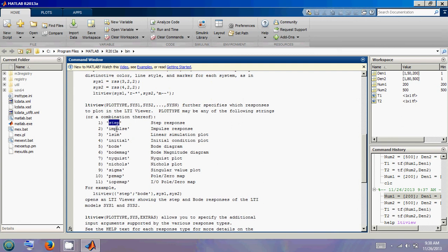If we ask to be given a step or an impulse input for the function, we would need to find the response for the input. And these two commands, if they've been attached to the LTI View command, will give a very nicely shaped output of the system response.